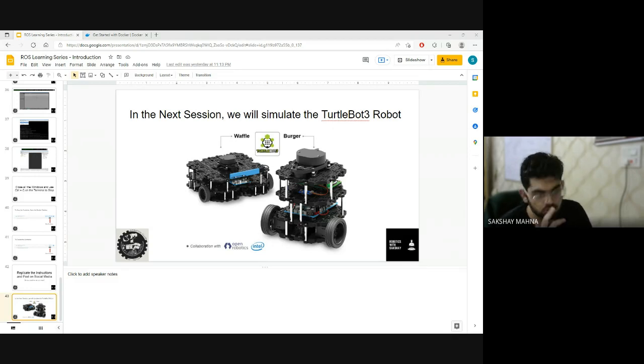You should not be running both of them together. We can have two separate terminals, one running ROS Noetic and the other running ROS Galactic, but we should not have it in the same terminal as such. Also, if you are interested in reading more about it, you can Google it as well. It's a well-known thing that people do, installing ROS with ROS 2.